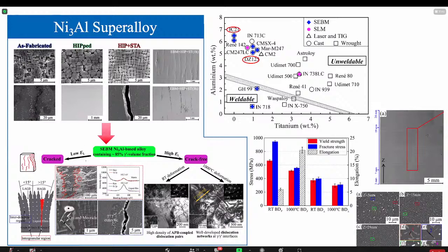We modified the processing parameters by using a very high laser energy input. However, when you give the high energy input, you will tend to have an uneven top surface on your powder bed. In this case, they will increase the probability of getting lack-of-fusion defects. So we then used a new scan strategy, combining this laser order with the appropriate laser energy. We then get this crack-free microstructure in the sample.